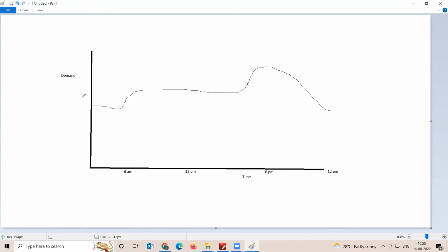Now, if I draw the solar power output, it will be something like this, right? Solar will not generate power before 6 or 7 a.m.; it generates, reaches a peak, and comes down before 6 p.m. Now, this minus this is the demand which has to be met: the demand minus solar power. Of course, I am exaggerating this graph, showing 30-40% of the demand being met by solar, but we have not reached that position. At max we are able to meet maybe about 15% of the peak demand in the daytime, at an instantaneous power level, with renewables.